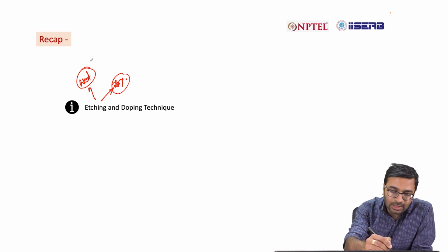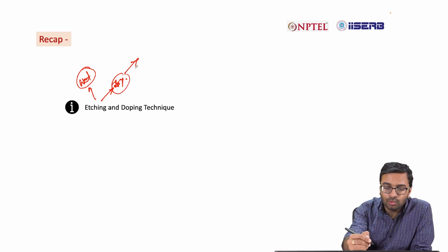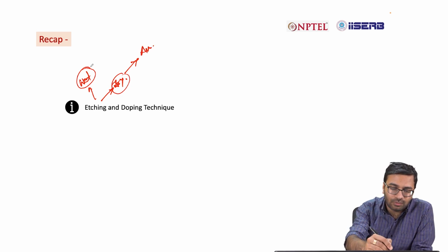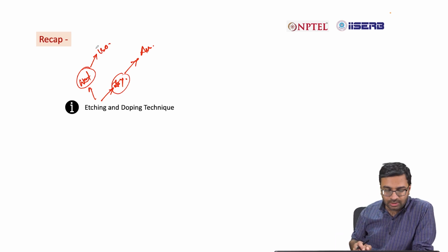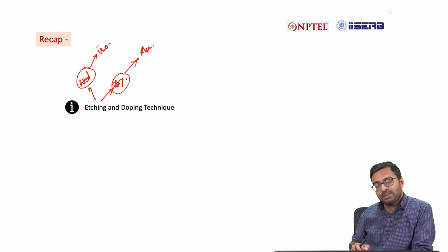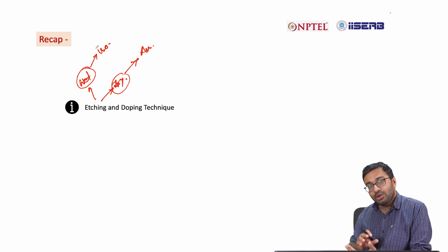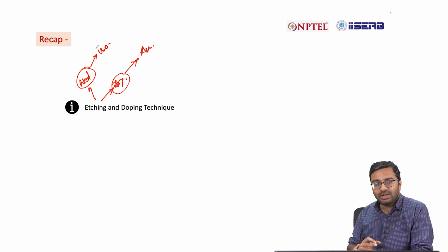For example, in case of dry etching, you'll be able to create a highly anisotropic structure. However, in case of wet etching, it's usually isotropic. Very difficult to create a highly anisotropic structure. But again, in case of dry etching, the equipment is very complex. Batch process is not something that one can make. In case of dry etching, it's very difficult to create a batch process. However, wet etching is relatively simpler, and you can go for a batch process as well.